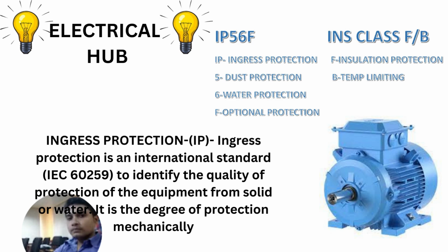So, what is ingress protection? Ingress protection is an international standard to identify the quality of the mechanical protection of any equipment. It is measured by two numbers. One is the first digit. For example, as you see in the drawing, it is 5. The first digit is for dust protection.